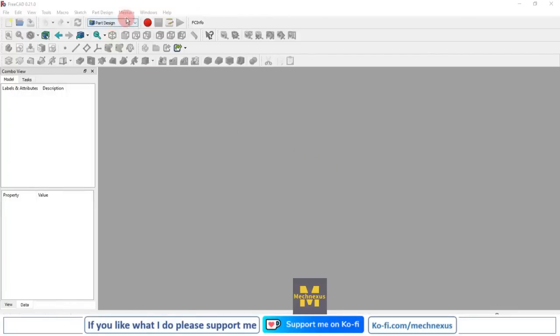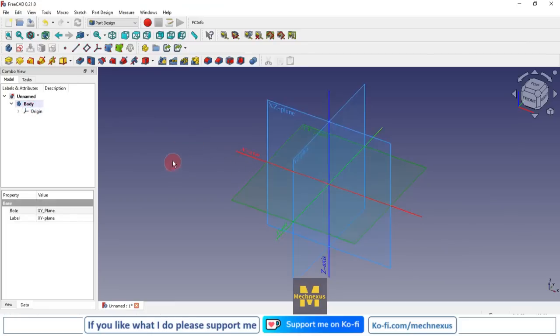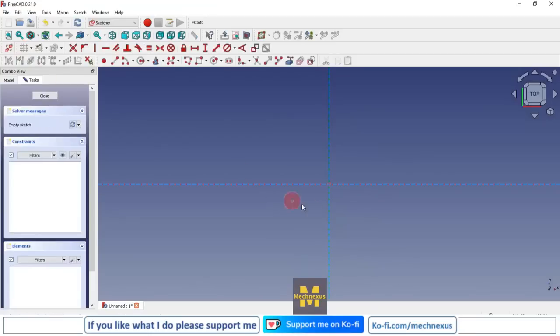So here I have activated the Part Design workbench. I will create a new file and then create a body, and on my origin plane select this XY plane and create a sketch.